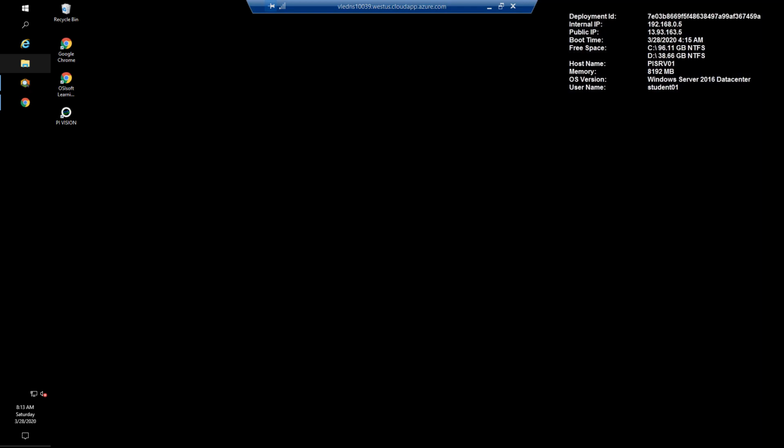First one being that FFS05 didn't appear as an asset in PI Vision, so we applied the template and that fixed that. The second issue we had was that the sugar grain size readings for form, fill, and seal machines 3, 4, and 6 were identical. This is because they'd been built using allow extensions and a copy paste. The copy paste is what led to the issue, so we disallowed extensions and based the sugar assets off of a derived template that took care of the naming pattern and all of that configuration.